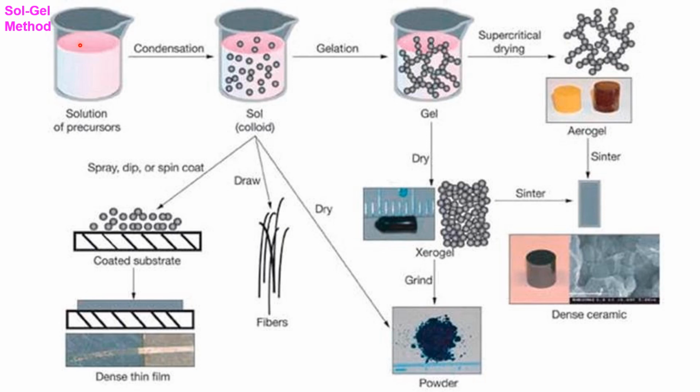This diagram shows the sol gel method, where the solutions of precursors are here, different chlorides or alkoxides. After some heating, they get some gelation or a network of the elements, and finally after drying, we can directly dry this and we get the gel in very dense form.